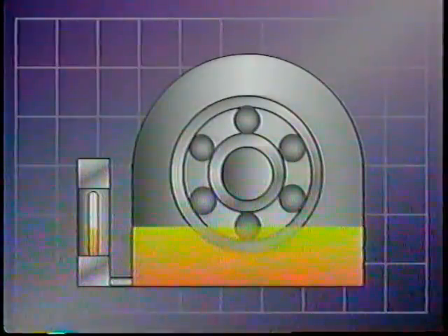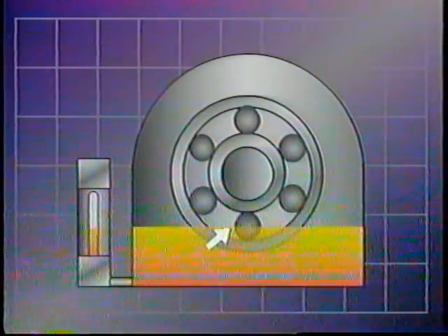For example, rolling element bearings are sometimes lubricated by running in an oil reservoir built into the bearing housing. Usually, the oil level should be no higher than the midpoint of the lowest roller or ball when the shaft is stopped.